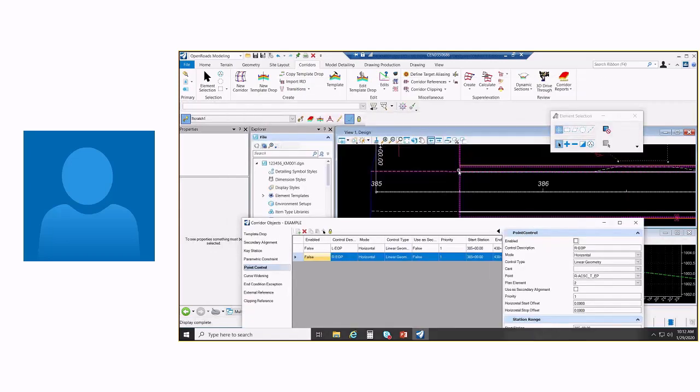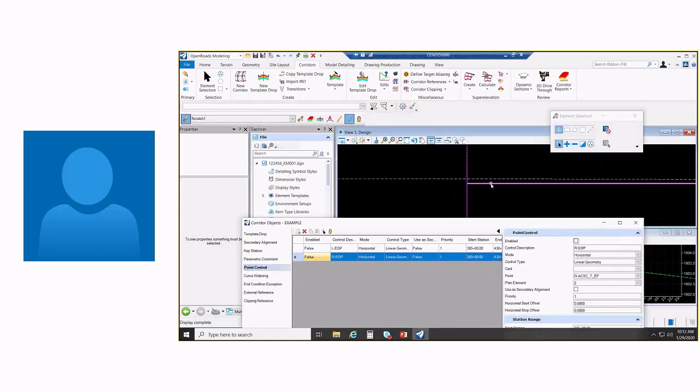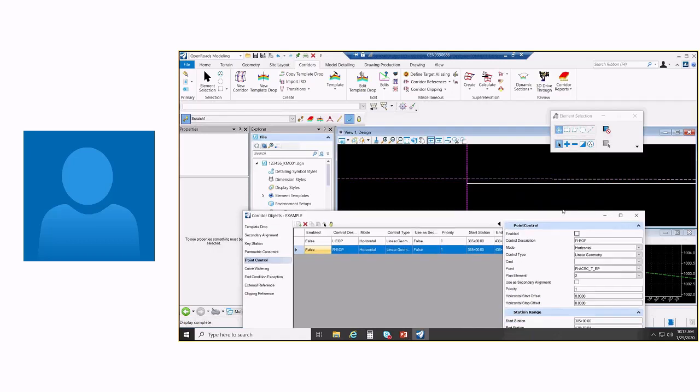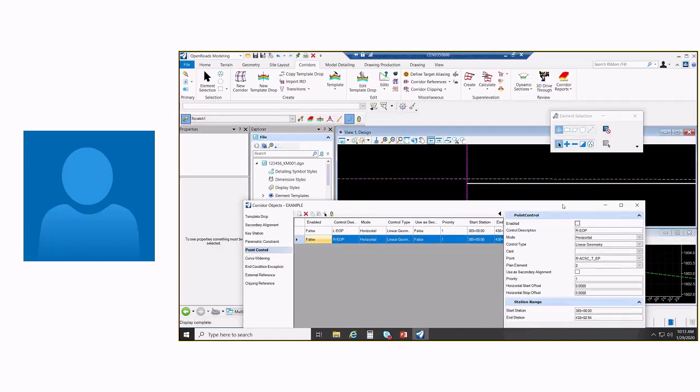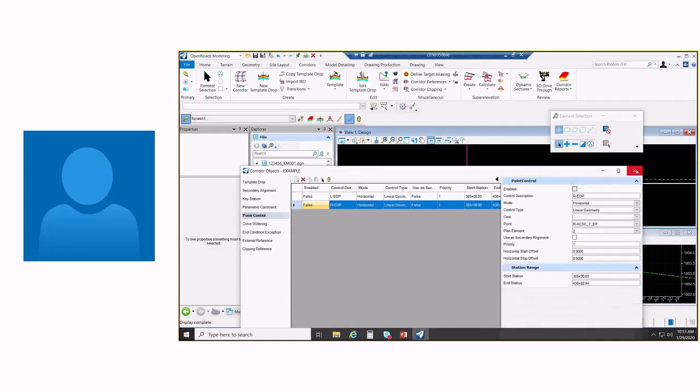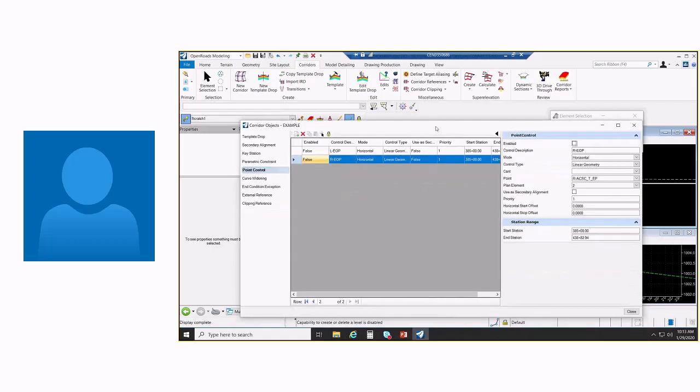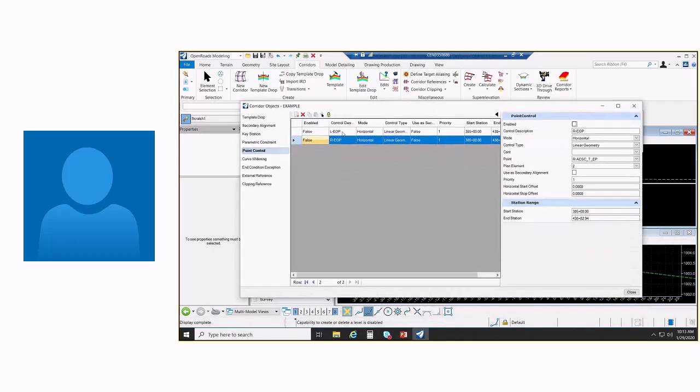So what that's done is brought it back to the initial template definition. So that top edge pavement, asphalt, concrete, surface course, edge pavement point is no longer constrained to meet that. What I'm going to do instead is constrain that left existing edge pavement point that I added. Actually, I could have just left those active and changed the point that's using here. I haven't tried that. Should I try that, JD? Why not? All right.